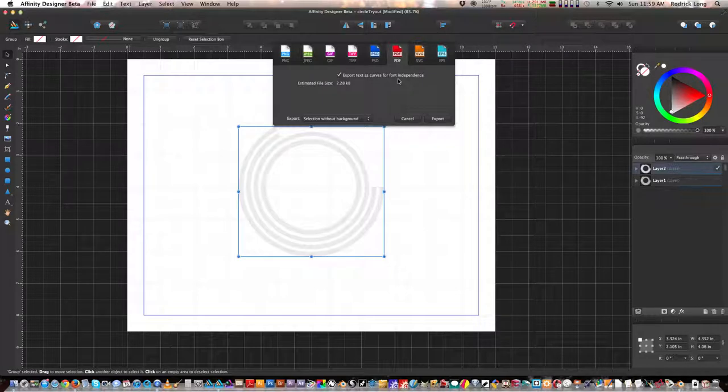If your font is OpenType, you'll want to export the text as curves straight from Designer and bring it over to Blender. Blender does not read OpenType. It has problems with it. Now, that's been my experience.